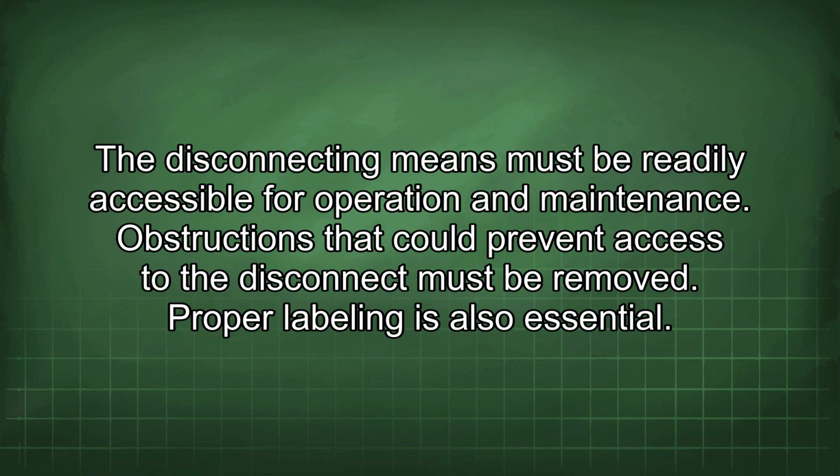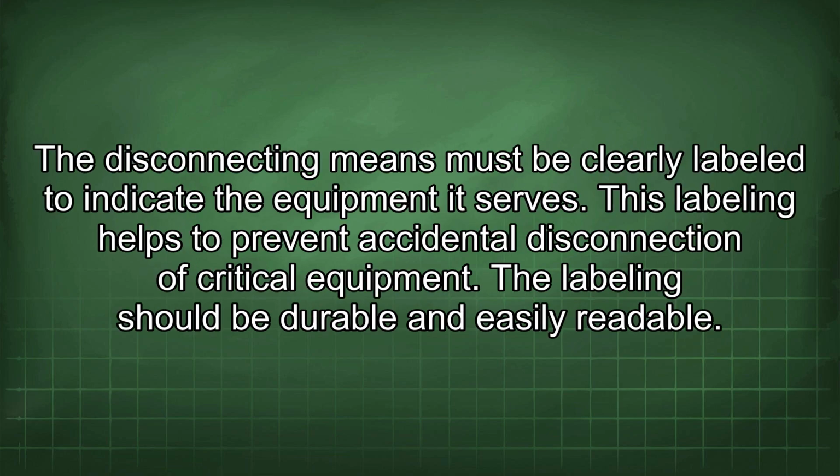Proper labeling is also essential. The disconnecting means must be clearly labeled to indicate the equipment it serves. This labeling helps to prevent accidental disconnection of critical equipment. The labeling should be durable and easily readable.